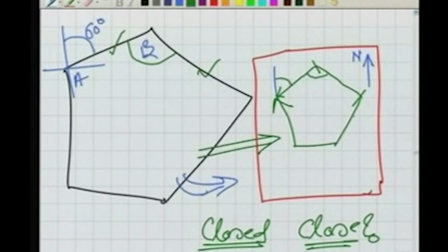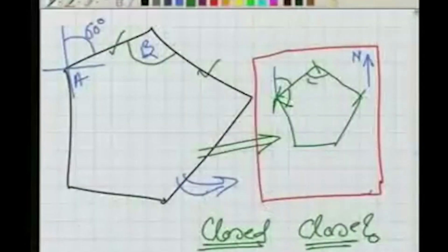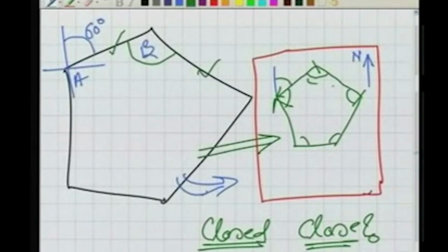After doing the plotting the way we have done, we have applied the correction for angles. Yes, our angles are now corrected, and the sum of all these angles satisfies the condition. Because here, if n is 5, the sum of these internal angles will satisfy the geometric condition of this traverse.